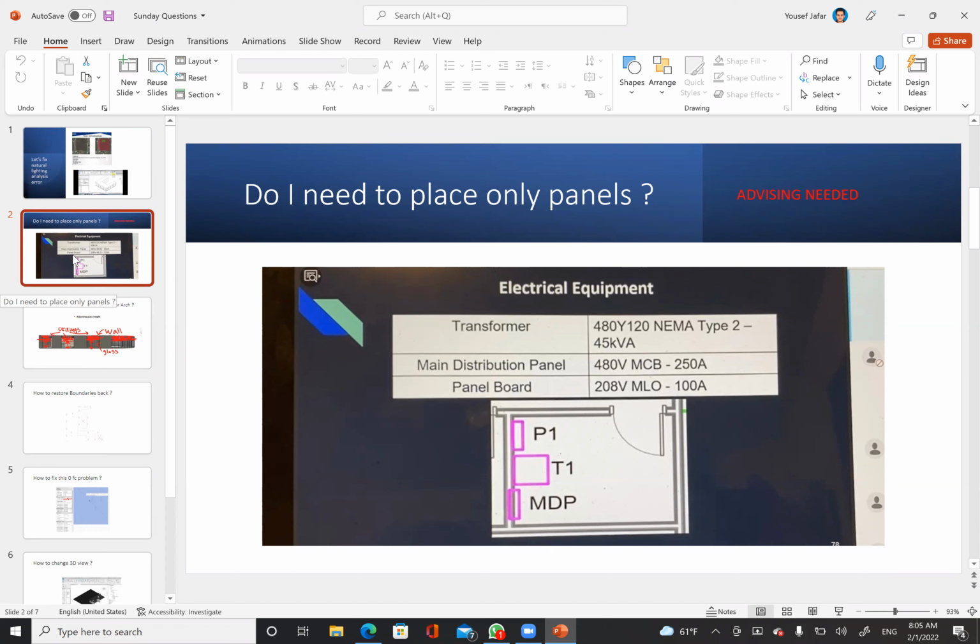Also, like that, we will be changing the transformer standard. In Revit, generally we have 480 by 277 and 208 by 120. This is the default value that we have. You don't have 480 by 250 available anyway. Okay, this one is the ampere rating, no? Yes, 250 is the ampere rating and 480 is the voltage rating. The ampere rating is again going to vary as per how many fixtures we have in that panel.